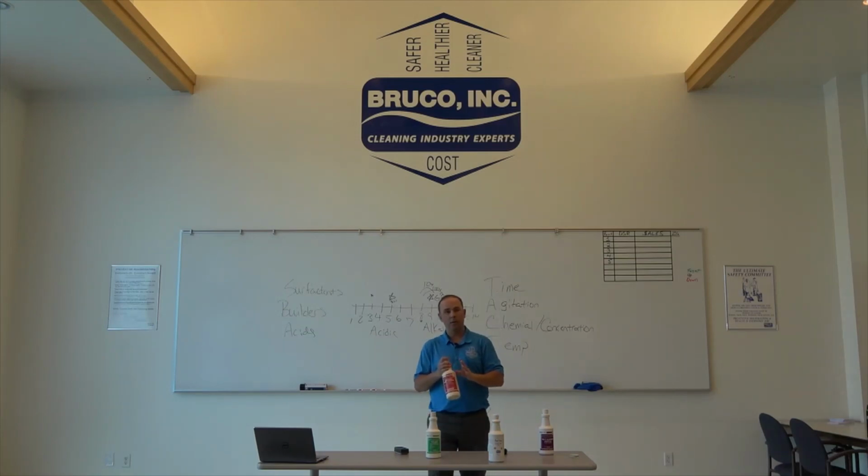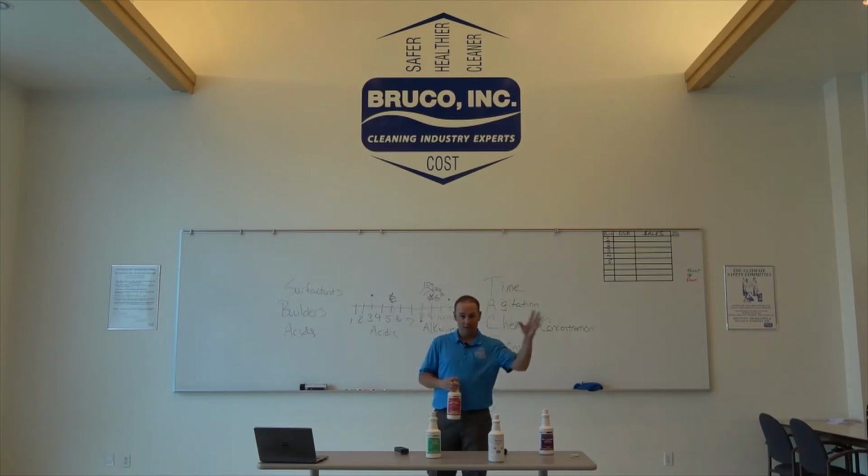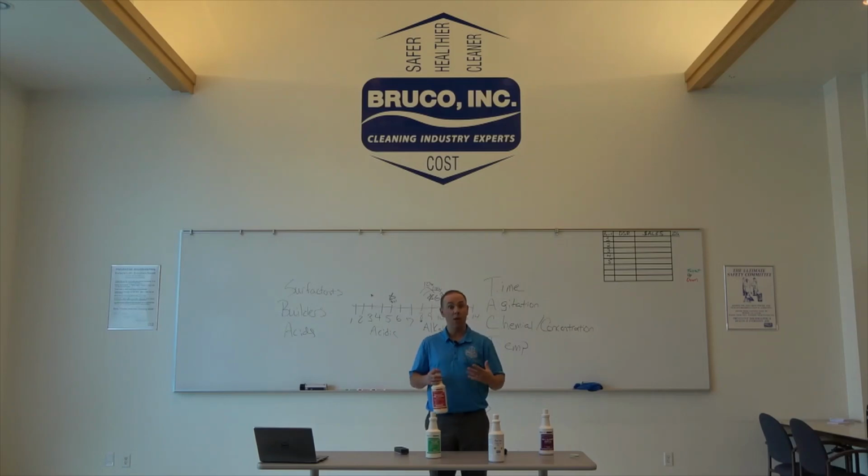This would be a 20% hydrochloric acid or the high teen percent hydrochloric acid. It should be reserved for maybe annual or semi-annual cleaning, or if we've got a couple areas that are really bad and get a lot of that red rust stain down on the inside of the bowls, or we've got some other type of major restoration project, when this type of product would be appropriate.